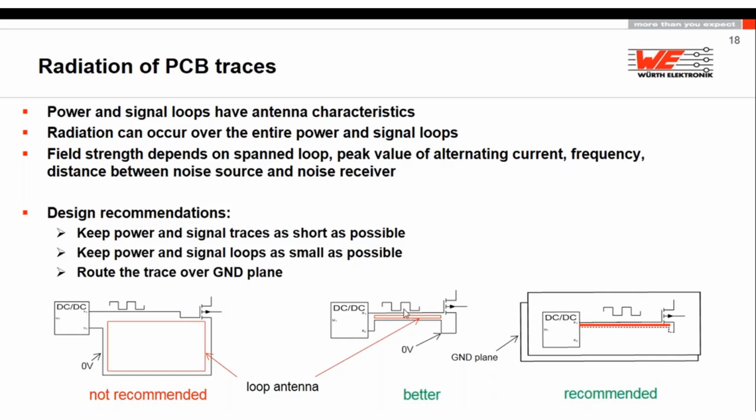And the best thing you can do is make a kind of PCB track matching, antenna matching at PCB level, so that you have the same length and the same distance to have the same impedance between the MOSFET and the controller. Then you can do a good thing. I like to do that in two layers: I put the track from the controller to the MOSFET on the top layer. On the bottom layer, I make an additional path, not just by accident, where the current comes back. I make a direct path back to the controller from the MOSFET, to be sure that this digital signal runs in this way. And then you have fewer problems, especially at high frequencies.